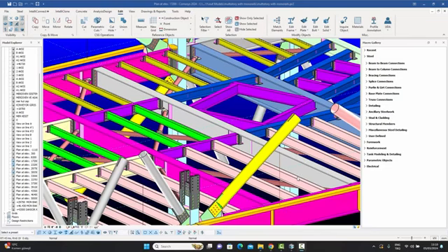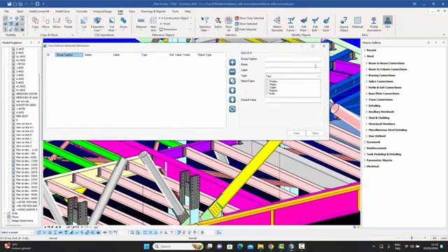Now, while explaining how UDAs work, let's press this button over here. Like I said, it's under the Edit menu. And when I press this button, this dialog box opens up. I want to go through this dialog box slowly so you can understand how UDAs are used. The first thing I want to talk about is what are the different types of attributes which you might need. And this is the type variable over here. If I open it, you see that it can be a text or a text list. It can be an integer or an integer list.